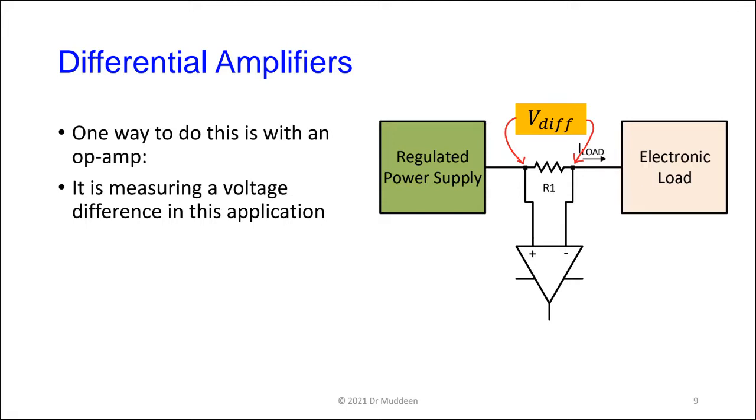Okay, and it's worse again because you're not grounded, right? You're wearing shoes, insulating soles and the like. You have that signal inside of you. So if there's a person on a bed and you stick electrodes onto them to measure the electric current passing through the heart muscle, the probes themselves are also going to pick up this common mode, or this 60 hertz signal that is around the place, and the amplifier has to be good enough to ignore that and only measure the millivolt or microvolt signal that we are interested in.